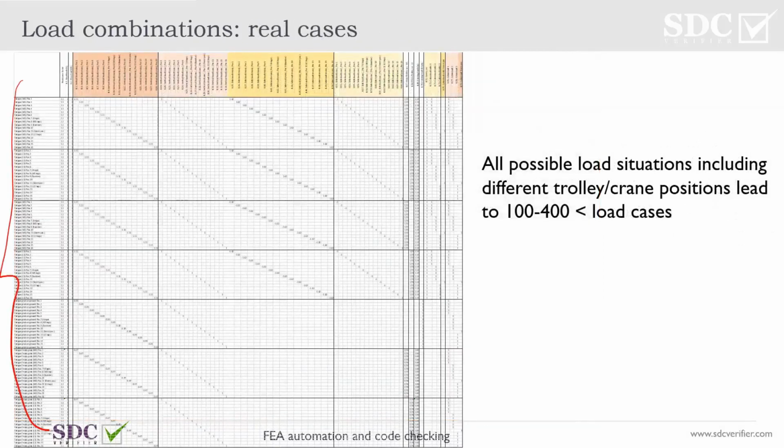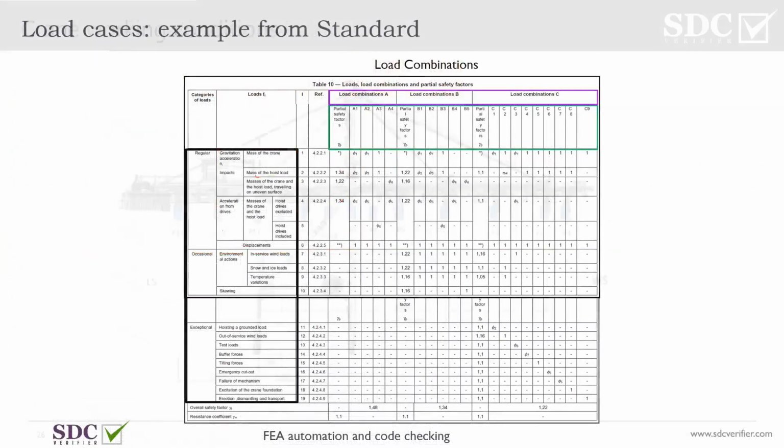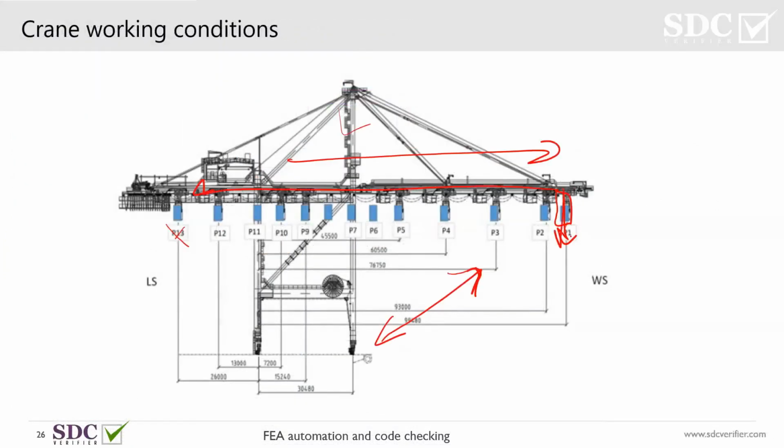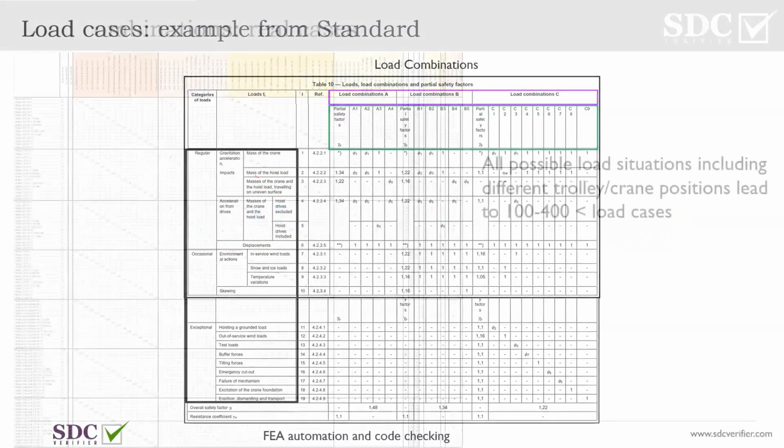when we're talking about these loads, what becomes crucial, I was explaining that, okay, if we have a vertical load, so my trolley lifting up the load with a certain mass, right? If it does it here, also here, so it creates a certain stress range, delta sigma. So the higher my load is, the higher my stress range is, of course.